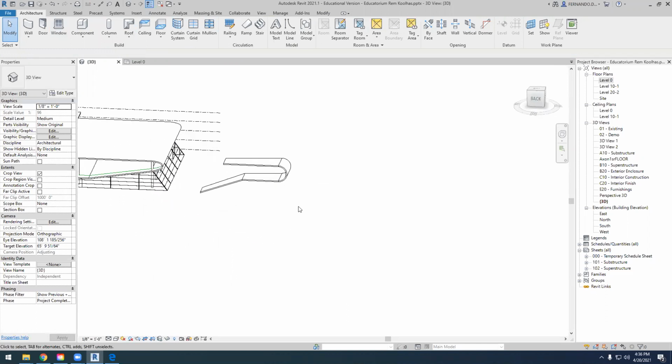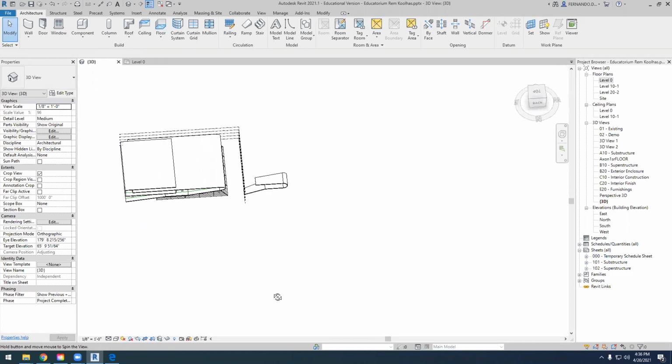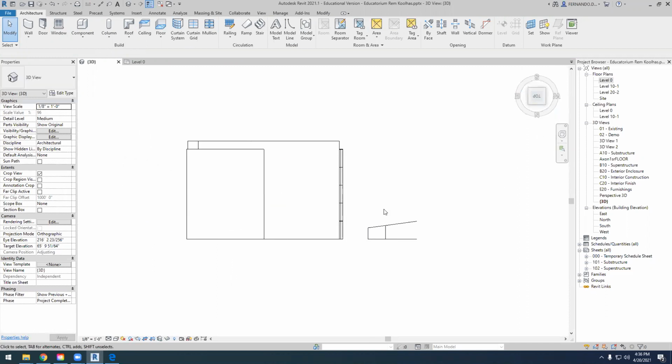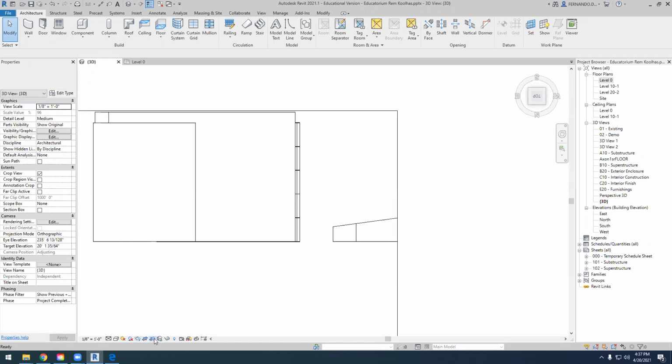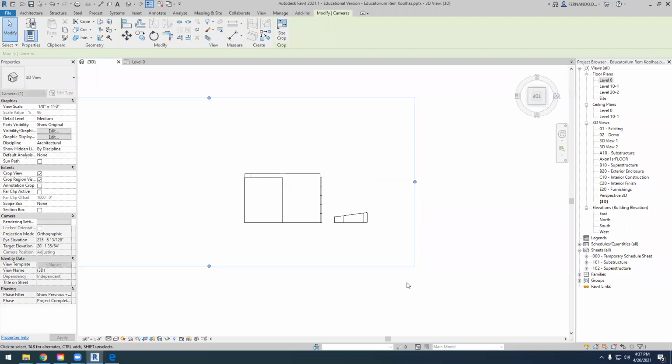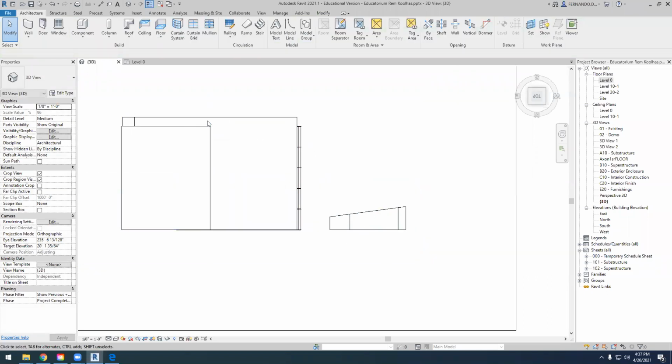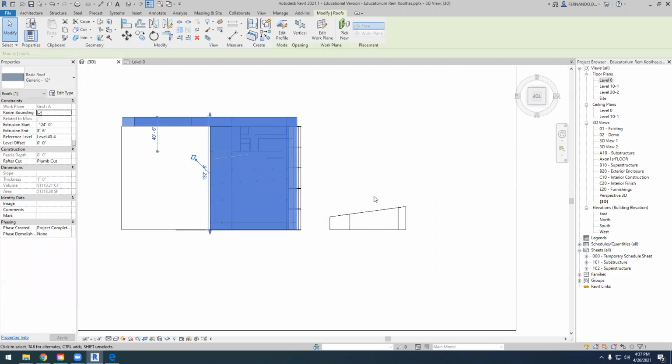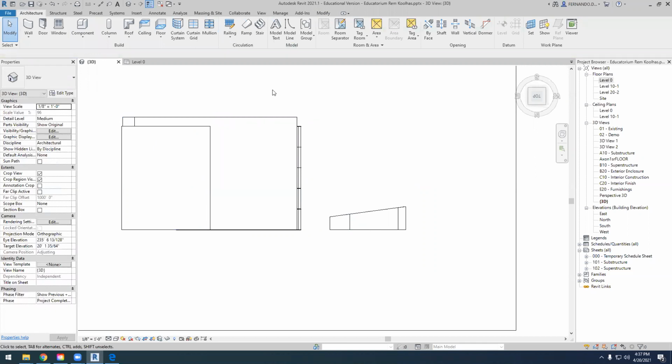So now I'm going to work with the massing inside because today's lesson is about subtracting volumes. We want to create a shape and then subtract the volume. This is what we want to do here. The problem is that we cannot do that because this is already a roof, and I can create a void form only if I'm working with massing inside. So I have to create a mass. It doesn't work if I create a roof or a wall. But there are ways to do this.